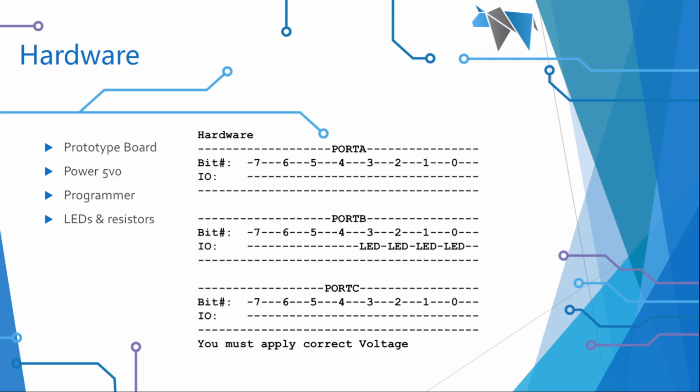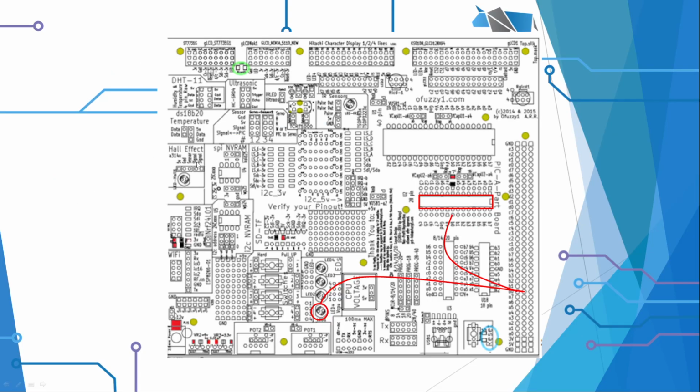And the sort of thing I'm going to be showing is a diagram like this. It's got ports and other things. And I'm going to be using today port B. Explicitly, I'm going to use port B.0, and on that I have an LED. It goes through a resistor. And my board layout is like this. I've shown you this on purpose because it supports an awful lot of stuff. And I've got the red chip sitting in my board in the PCB. It's exposed in a row of headers, and I've connected that row of headers to an LED.